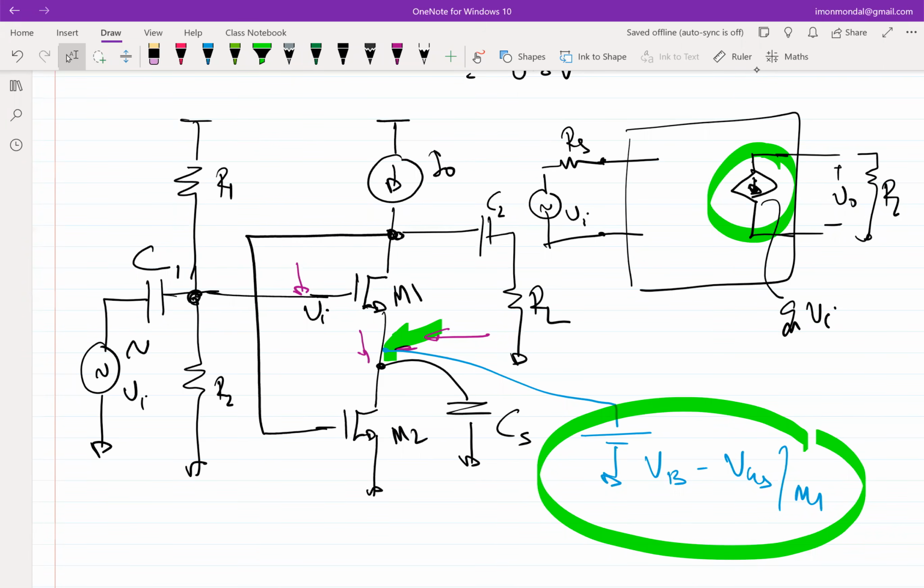One is you apply a voltage and figure out the current. The other is you apply a current and figure out the voltage. When I say something is high resistance, what I'm essentially saying is that if you inject a current, you will have a lot of voltage change. But negative feedback is preventing that, because by design you are trying to ensure that nothing changes, right? You would only want the change between input and output, but nowhere else in the loop should get affected.